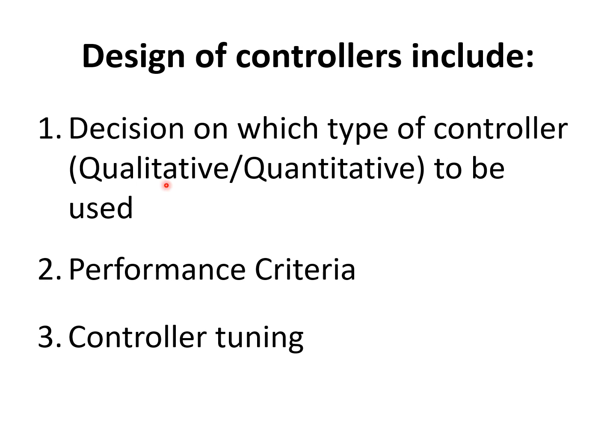Qualitative, based on experience, on our knowledge of how the controllers work. And then after that, we'll also have to talk about controller tuning. As I said, sometimes the controller tuning can be related to performance criteria. If you use ISE, it will also solve for the controller tuning as well. But there are also fixed methods of control tuning. There are also methods related to the performance criteria to get the control tuning, which we just mentioned later.